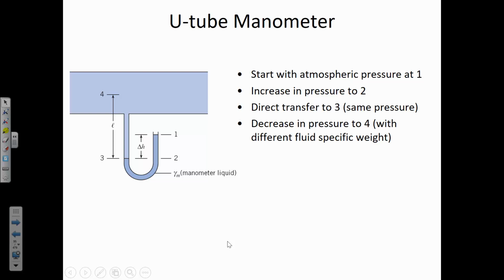And you'll remember that when we were talking about piezometers last time in class, I said the way it works is we have some pipe and a fluid is flowing through the pipe, and if we puncture the pipe, then stuff would start spraying out if it's a liquid. So instead of allowing that, we connect a secondary tube that goes up, and then the water level will rise to a certain elevation consistent with how much pressure there was inside of the pipe.